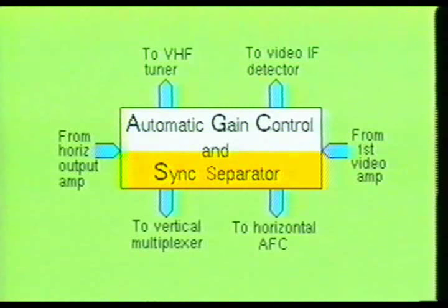The sync separator portion of this stage is designed to remove the sync pulses from the composite video signal. These sync pulses are then used as timing signals and are fed into the vertical and horizontal deflection circuits.